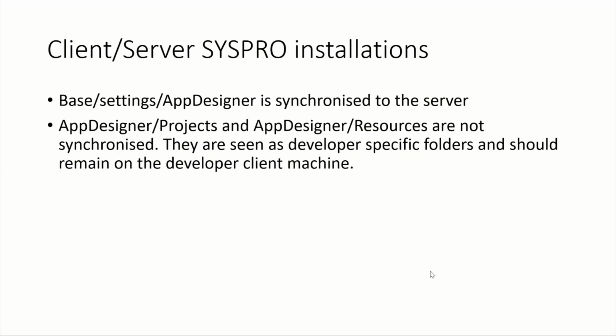If you are working on a client server installation, note that the apps themselves, the appdesigner.txt files in base settings app designer, are synchronized to the server. This makes sense because they are actual programs and they will be required throughout the client server installation. But the projects and resources folders are not synchronized. We see these as developer specific folders and should remain on the developer client machine.